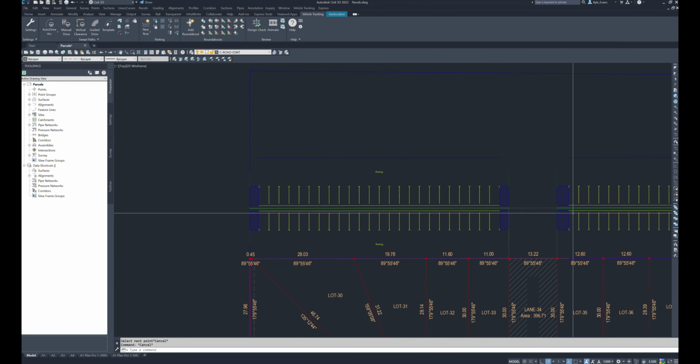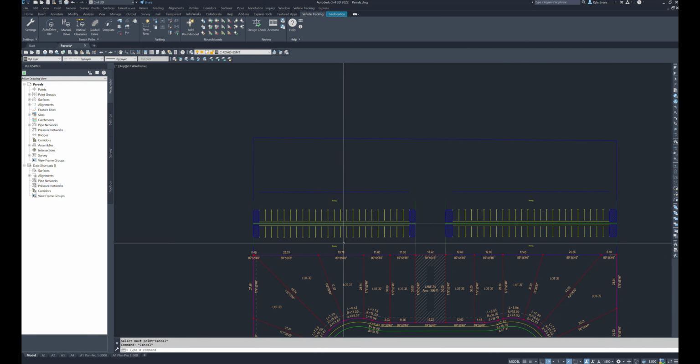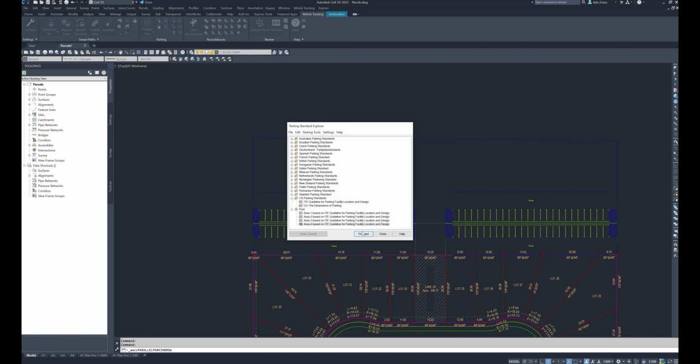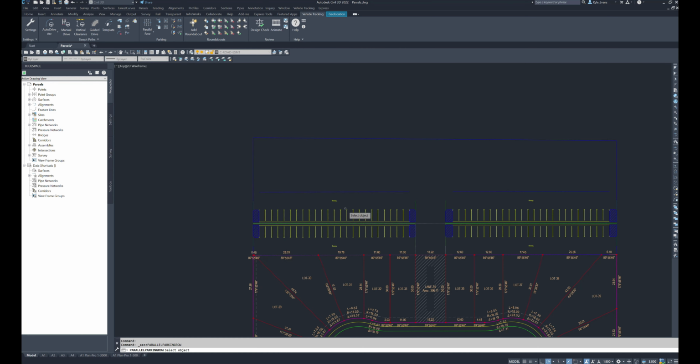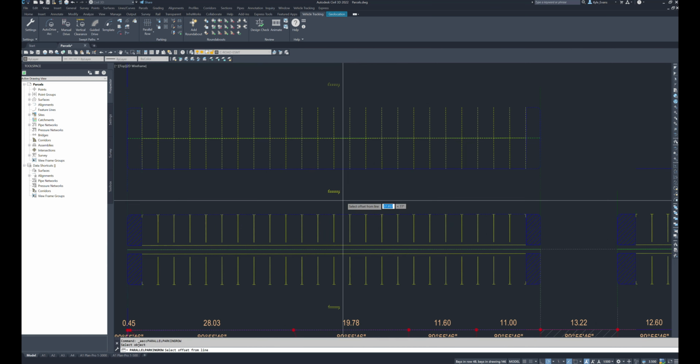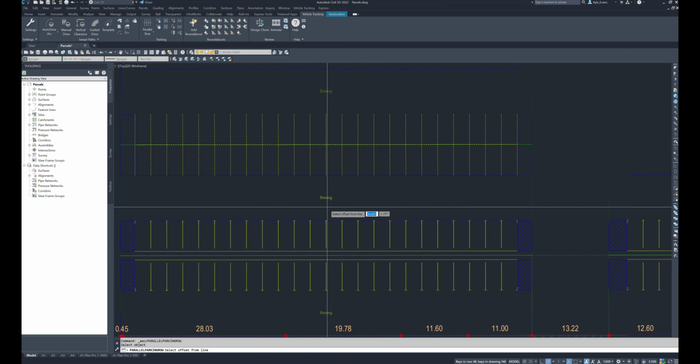So I've basically created 2 sets of parking bays. We haven't done any numbering. We haven't done any switching of standards yet. We're going to do a new parallel row. Again, the same dialog box pops up. We could modify these for what we need. We can do it afterwards. We're going to change things slightly afterwards. I want it parallel to this, and we can adjust where we place it now, and it's going to place it parallel. Now, right now, these are set for 2-way roads, so this is about 7 to 9 meters wide